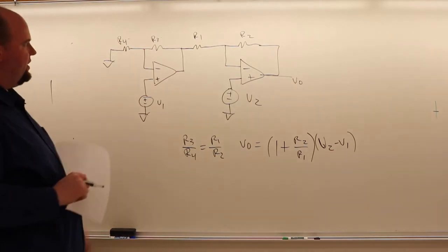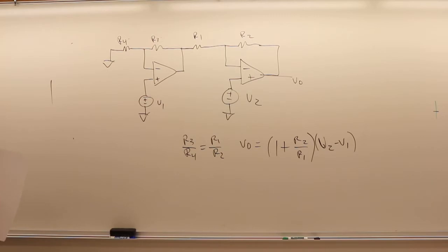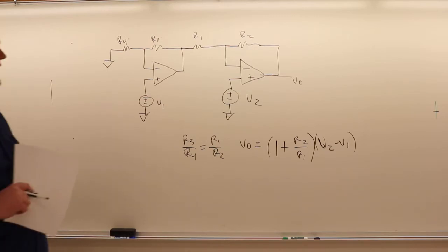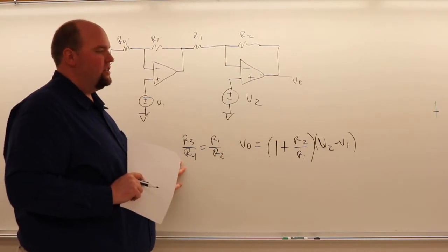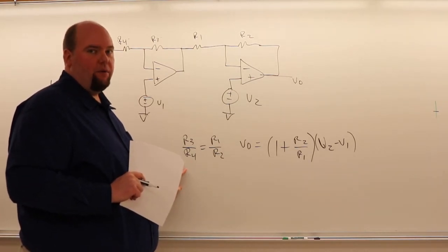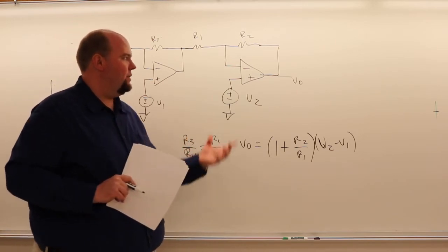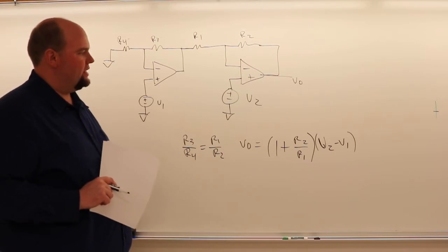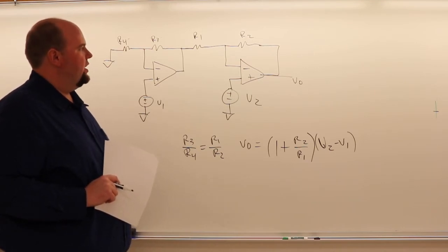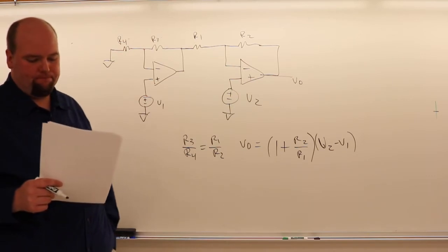Now, the downside of this, though, this is a dual operational amplifier. The downside is this does not have variable gain right now. So in this case, these resistor values would have to maintain this ratio. They would be built into the chip. We would not have access to them. What if we did want to take this same design? We've found a way to make a high input resistance operational amplifier with only 2 op amps. What if we wanted to add gain here?